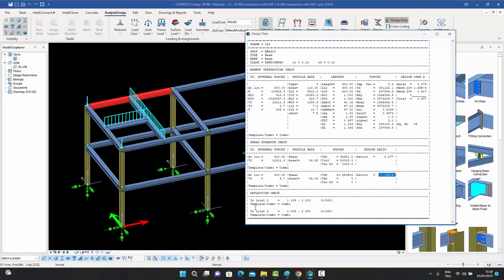If you want, you can even get a deflection check. So over here, it is 1.135, less than 1.2 centimeters, which is okay. All these are details which you already know regarding how to do the design. Obviously, the deflection check has got nothing to do with the Indian standards. But this top part over here is what I'm talking about.